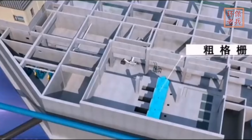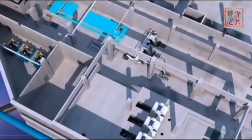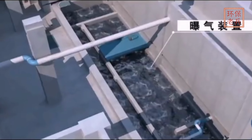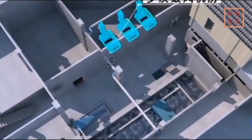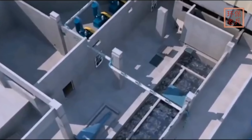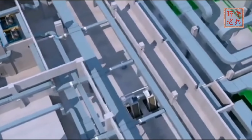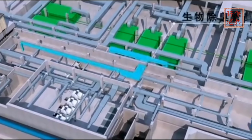After secondary interception by the coarse and fine screens, the wastewater flows into the aerated grit chamber. The aeration device is installed on one side of the grit tank. As the wastewater enters, the root blower room supplies air through air diffusion plates to remove organic fumes attached to the surface of the wastewater. Off-gas generated during aeration is discharged into the atmosphere after biological deodorization.